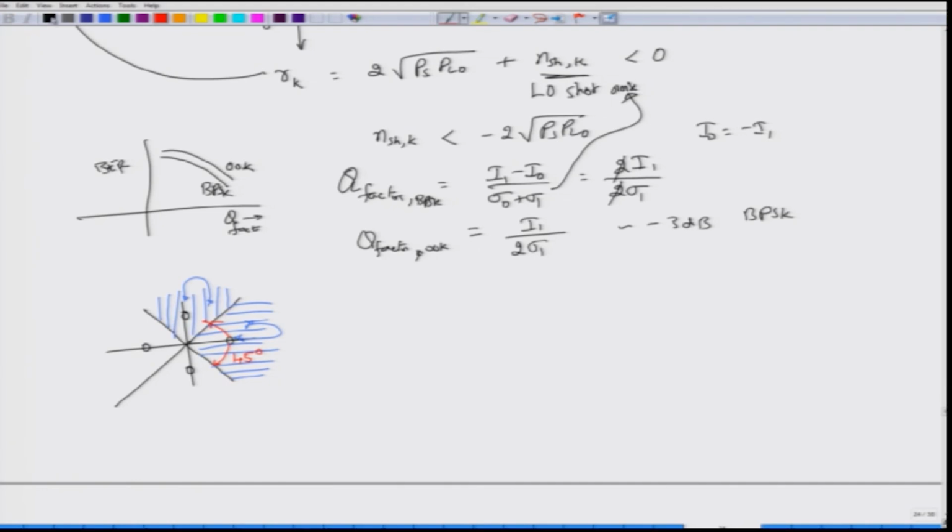Okay. If you now start going to higher order modulation, for example, we talked about an 8 array PSK modulation, right. So, you can see very clearly that the decision regions corresponding to this would then be even more closely spaced. Okay, so this is one more decision region, so you are going to get, that should have been over here. But the point is to note that the phase noise margin starts to decrease again here, right. So, from 45 it should become now 22.5 degrees. So, as you start packing in more and more constellation points, the allowable phase noise margin degrades.